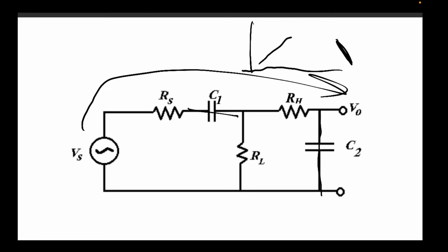So maybe you can intuitively think, oh, in the middle, it's probably not 0, somewhere in between, probably somewhere flat. And then there will be some frequency here, FL, and some frequency here, FH. So that's how, for a simple circuit like this, you can easily derive a transfer function, right? Just by looking at the properties that these capacitors hold, or where they are.